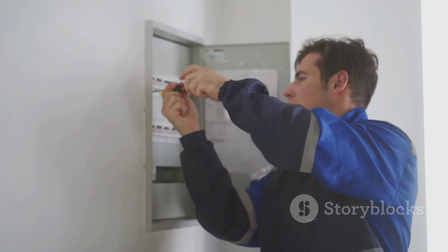Section 8. Bringing it all together. A sample distribution board design. Let's put everything together with a simple example. Imagine a small office with the following electrical needs. Lighting: 10 LED lights, each drawing 10 watts. Sockets: 6 twin sockets, each rated for 13 amps. AC unit: 1 3-phase AC unit, drawing 5,000 watts.